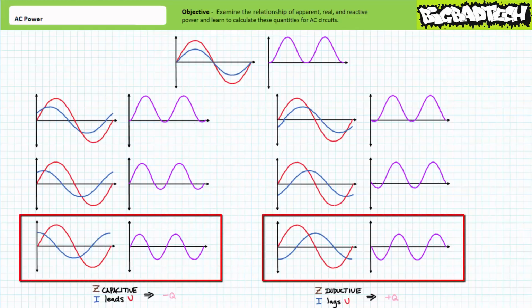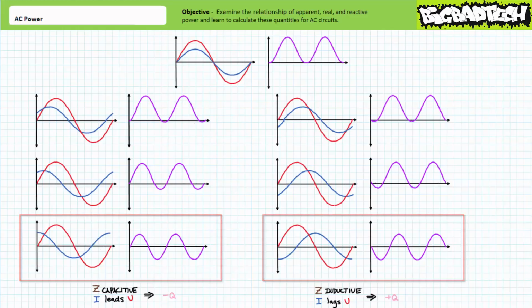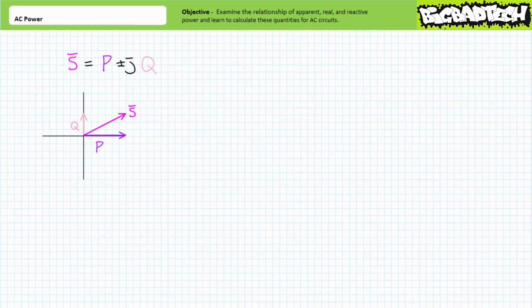Finally, when the differential between voltage and current reaches a full 90 degrees, either leading or lagging, none of the apparent power is being directed towards real power because all of it is being directed to the reactive exchange. One might think this relationship, as real decreases, reactive increases, and vice versa, to be linear, but it is far from being so simple. This being said, it's not hard given a thorough understanding of complex numbers.